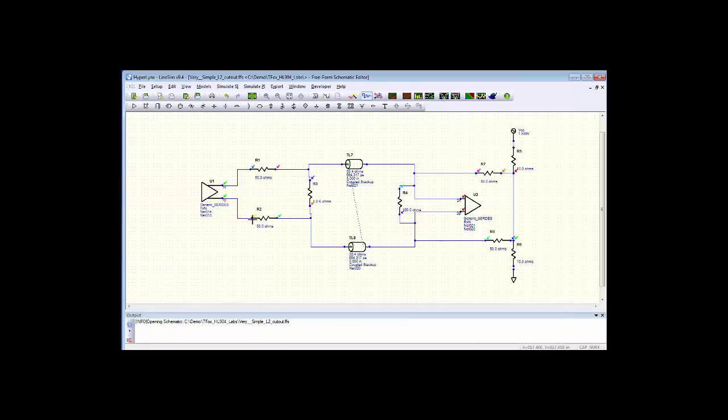So if I look at a common mode signal going here, a 50 ohm roughly drive point, a 50 ohm transmission line, a 50 ohm termination to VTT, that's fine. If I look at this thing from a differential standpoint, then I've got some signal at this point, and across this 100 ohm differential line, I've also got a 100 ohm differential termination.